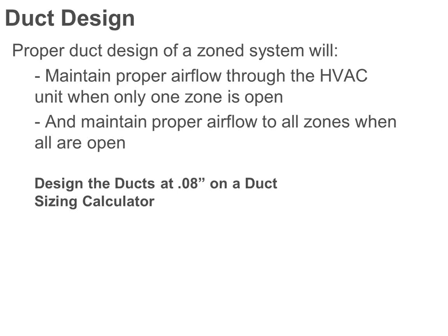In terms of duct design, for the most part, all the branch ductwork you're sizing the same way you would have previously sized it, right? How much CFM do I need to get to this particular room based on its peak heating and cooling loads? The main supply ductwork, in the perfect world, you'd be sizing for the overlapping peaks, right?